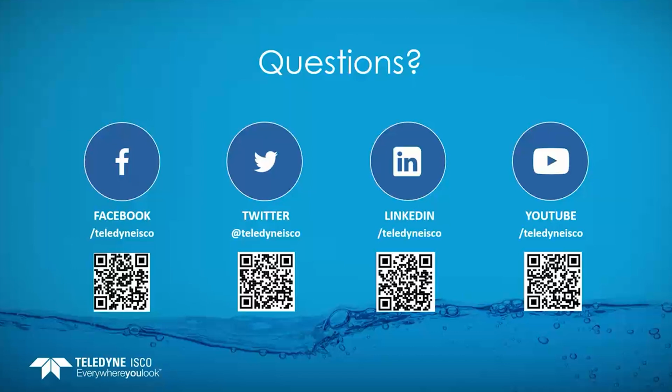Okay, here's another great question. Why use a flume over a weir? Yeah, that's a great question. One right off the bat is sedimentation. If you're going to be in a situation where you have a lot of sediment running through your effluent, a weir is going to fill up quickly, depending on how much sediment is in there. You have a lot of sedimentation falling into the bottom. They need to be maintained more often, and they need to be drained and cleaned.